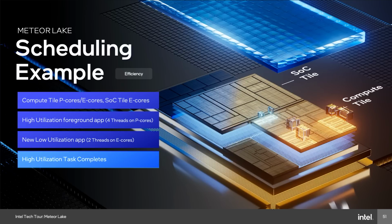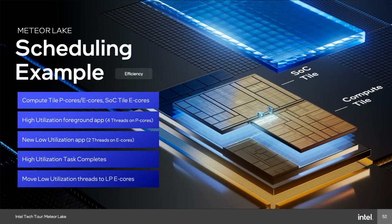But once my foreground high usage work, if I'm running a game or content creation, is finished, and I only have that low usage activity, then Thread Director reflects back to the OS saying that, hey, the efficiency ordering has changed. The SoC tile is more efficient, so the work can move there, and we can power down the compute tile. So all of this gets communicated to the OS from hardware in terms of this Thread Director table that we provide. That's pretty cool.